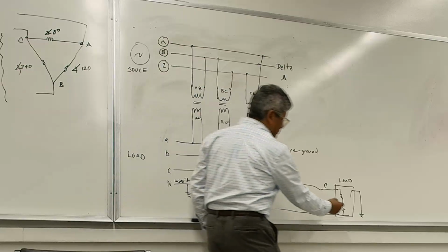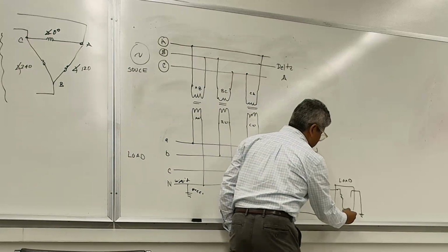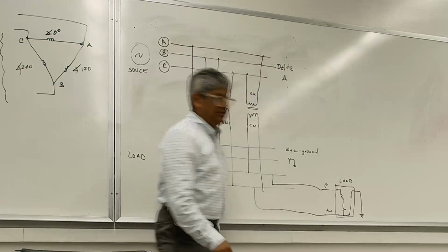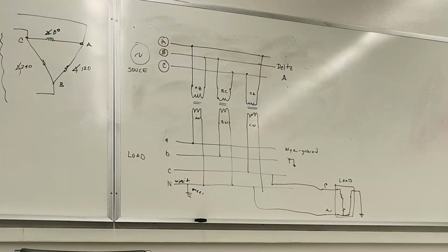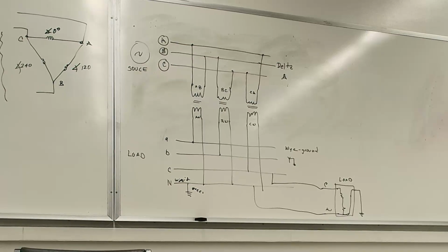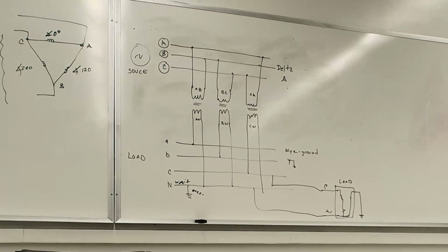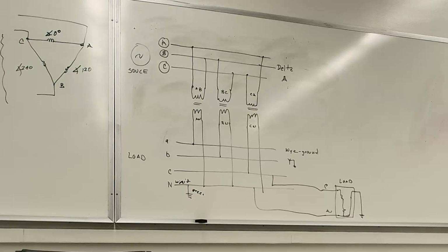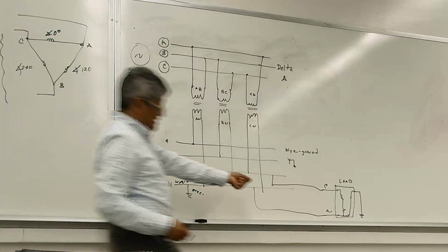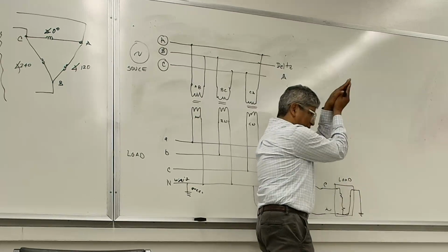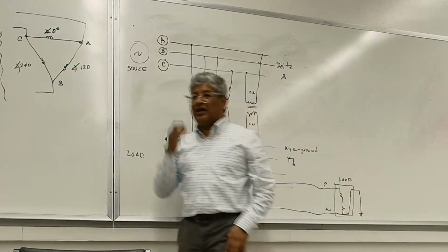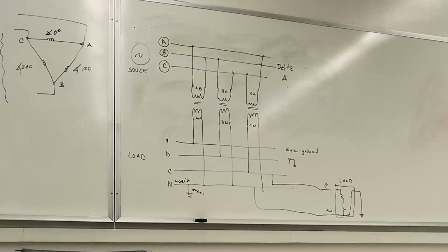So it's very easy for somebody to say, and I don't want to bash technicians, by the way, because you have to work with them and they know their stuff too. But somebody comes and complains and says, hey, my phase-to-neutral voltages are not as good. It seems like my neutral is bad. I don't have a good solid neutral. So they measure right between the neutral and the cabinet, and they say there is a voltage. Oh, they need to ground it, so I bring everything to zero. You cannot do that.